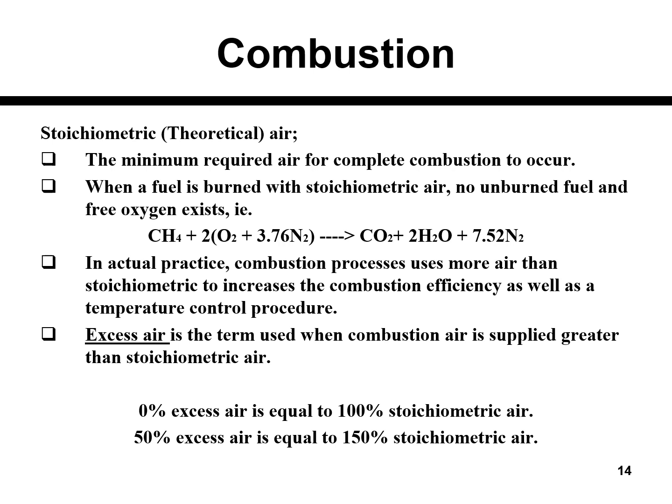Okay, and then for stoichiometric or theoretical air combustion, this is the minimum required air for the combustion to complete. When a fuel is burned with stoichiometric air, there is no unburned fuel and no free oxygen. For example, for methane, CH4 plus 2(O2 plus 3.76 N2) produces CO2 plus 2 H2O plus 7.52 N2. We're going to do this analysis during the synchronous class.